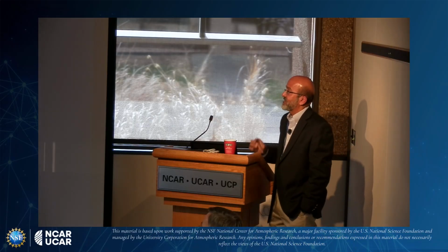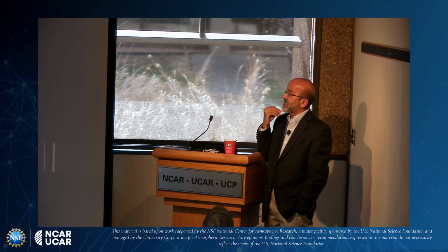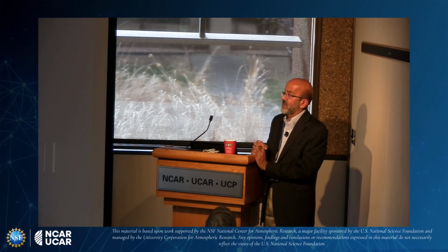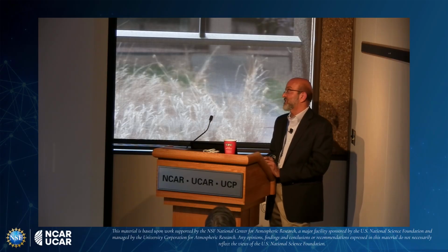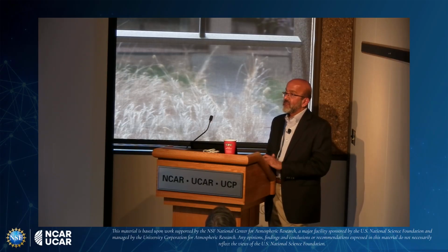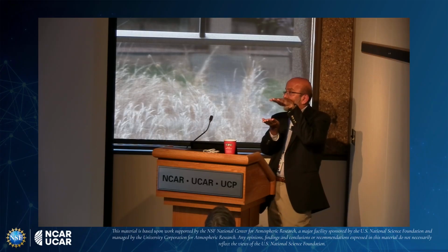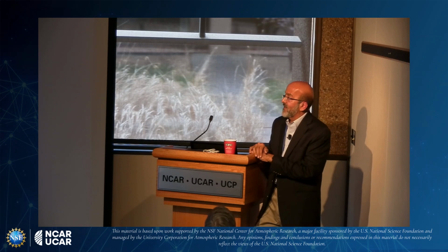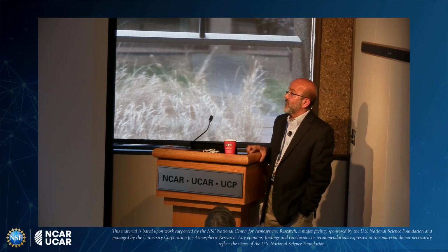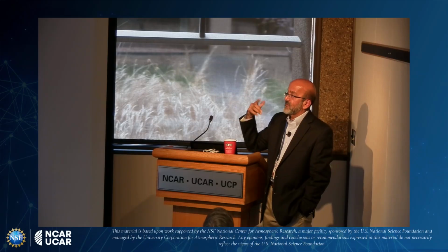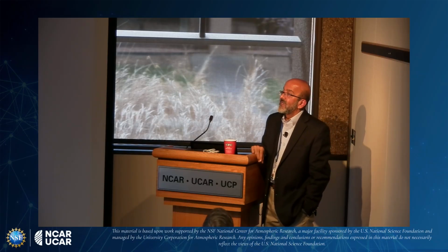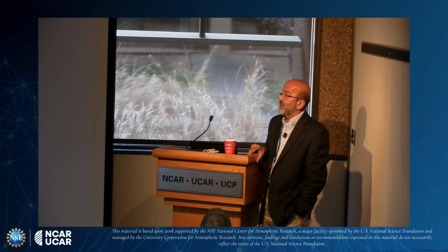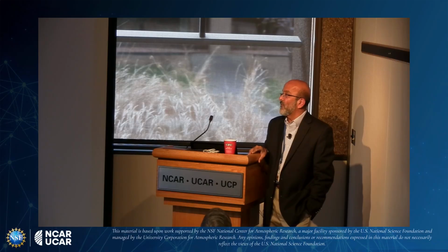Yeah, so I love that question. I think the question says, can I dope portions of the interposer to make resistors or capacitors or something? The short answer is no, but this could be a fun thing to try. But again, the interlayer spacings on the interposer are far enough that you wouldn't get good capacitors, for example, if you wanted to do that. So I think that there's no process natively from the interposer vendors I'm talking about to do something like this. If I wanted to do it anyway, I wouldn't get a high enough capacitance density to warrant doing this, I guess.